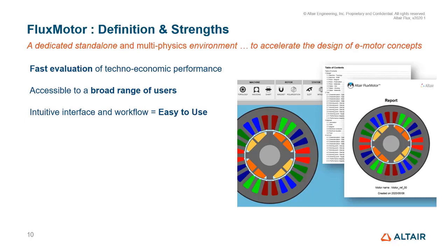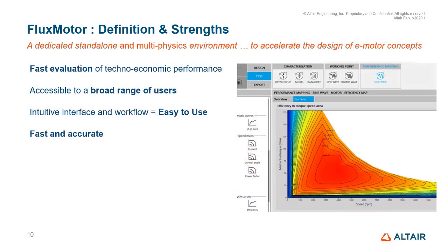With no simulation knowledge needed, it has customizable templates which are completely parameterized, a user-oriented winding tool, and predefined tests with automated reporting, and you can literally build the machine, test it, and produce the report in a matter of minutes, not hours. It's really fast and accurate. It uses a mixed finite element solver in the background, and also some analytical calculation with embedded modeling knowledge about e-motors, and also an optimization process in the background.